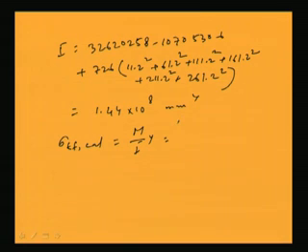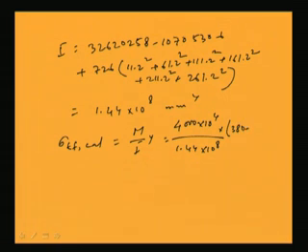So, M is 4000 kilonewton centimeter; if I make it Newton millimeter, then this will be into 10 to the 4 by 1.44 into 10 to the power 8, this is I, into y, which is total 380 minus 40 minus 78.8, because neutral axis depth is 78.8 from bottom, then 380 minus this, minus edge distance. So, from this I can find out 72.5 MPa. So, in this way I can find out this value.